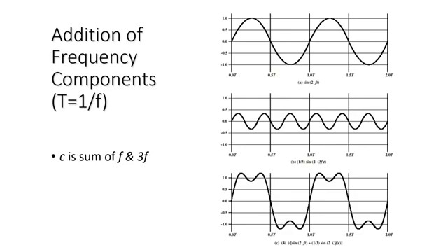As mentioned before, a signal is made up of components at various frequencies. Basically, it is a combination of different waveforms. In the figure, we see two different sine waves in figures A and B. Figure A is our traditional sine wave with an amplitude of 1, frequency of 1 Hz, and phase of 0. Figure B is a sine wave with an amplitude of 1/3, frequency of 3 Hz, and a phase of 0.